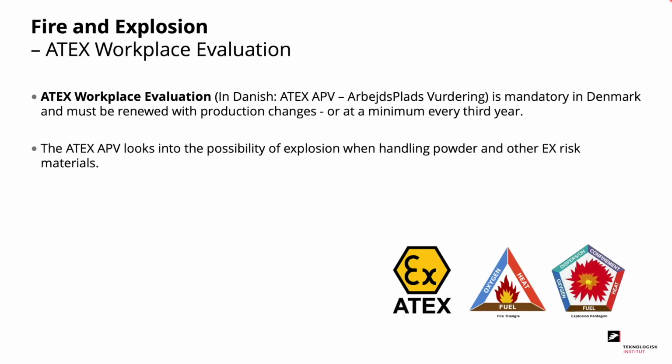Regarding fire and explosion, you need an ATEX workplace evaluation. This is mandatory in Denmark and must be renewed with production changes or at a minimum every 3rd year. The ATEX workplace evaluation looks into the possibility of explosion when handling powder and other explosion risk materials.